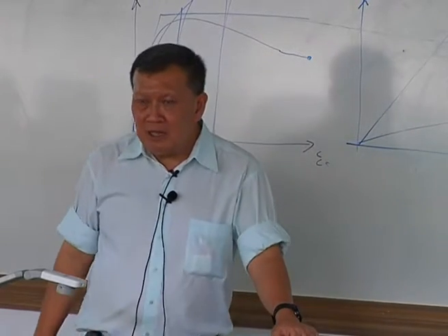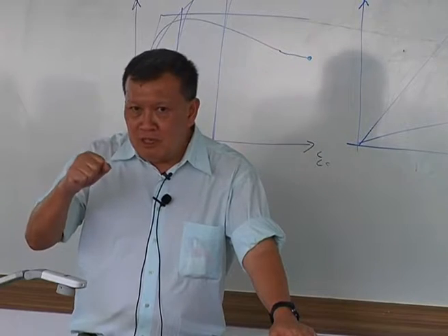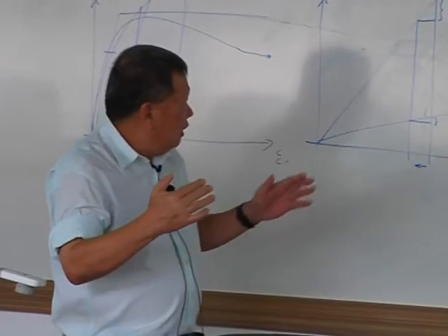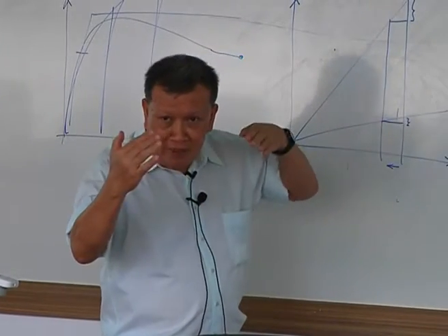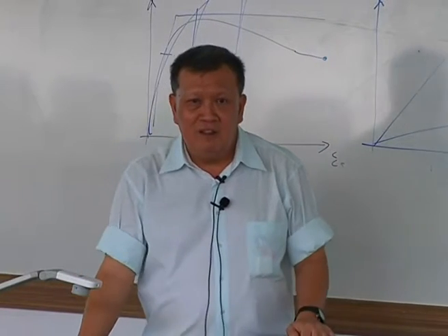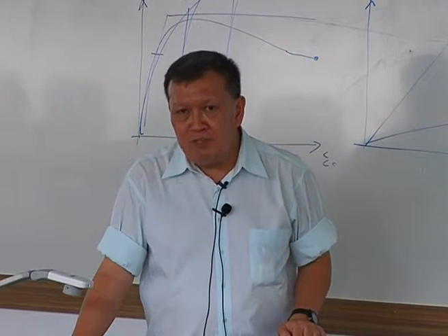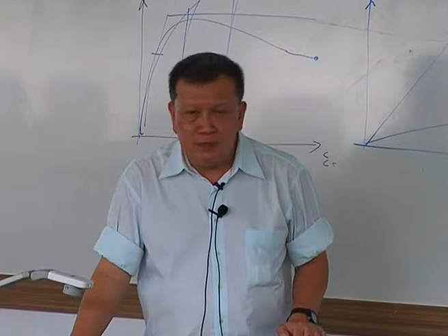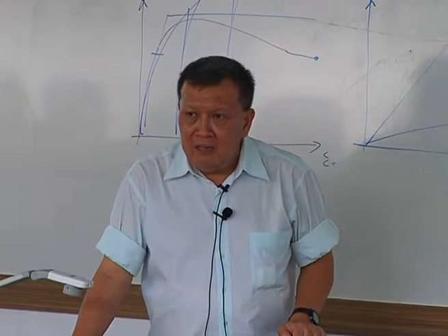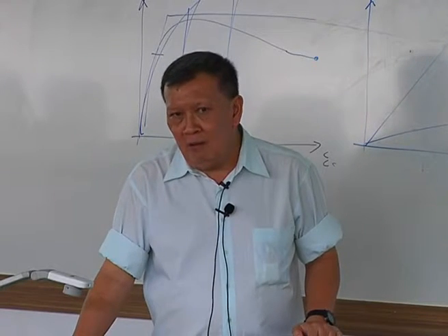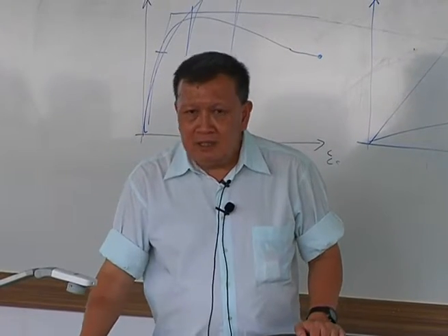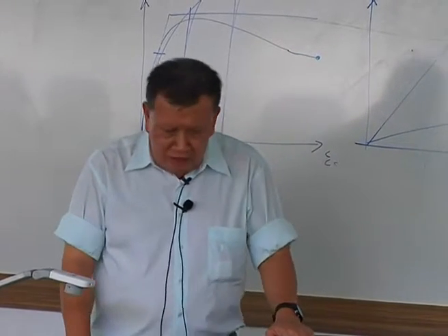The second reason is that because the strut is stiffer, by analogy, if you have a movement forward in this direction, some compression effect, the strut will pick up load faster. It's much more positive. So the strut is more positive. It's almost exclusively strut. Now, in anchors, I have seen people use anchors, but only by hillsides, not in the city area, way out in the countryside kind of thing. That's another issue, going into other people's property.